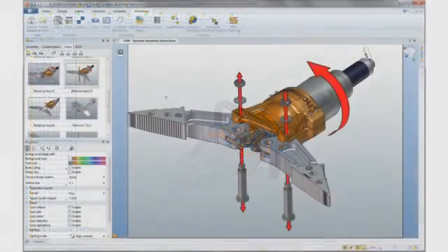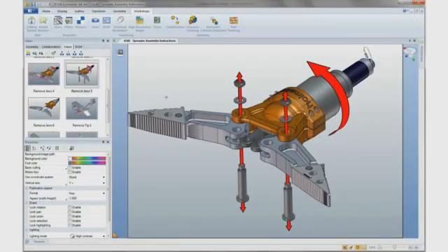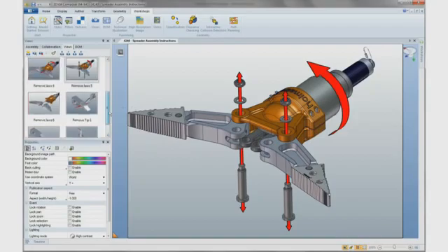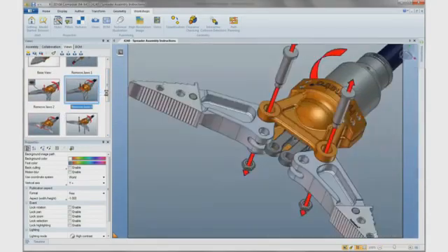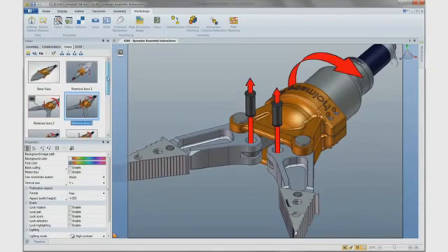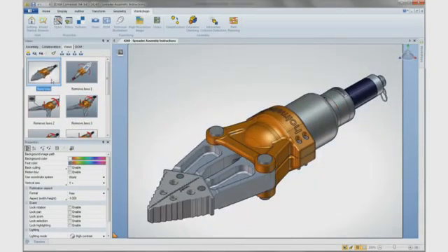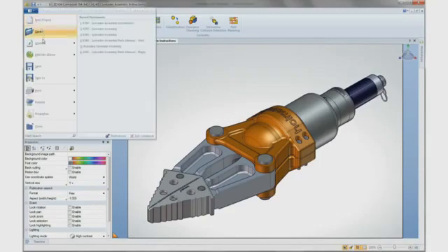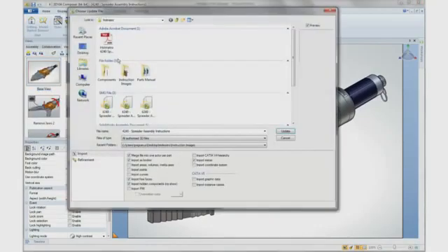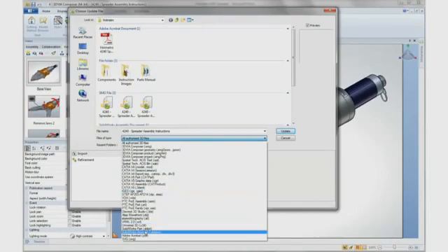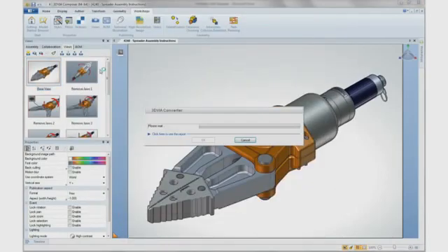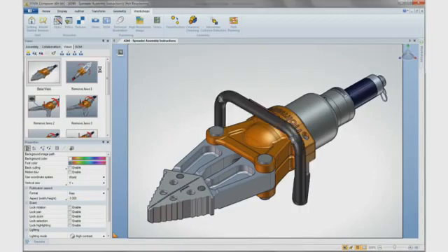The creation of this manual was well underway before the design had been finished. We can see that none of the views contains the handle assembly that was recently added as a design change. Thanks to SolidWorks Composer's associativity, we can see how a change within the engineering software will affect the work in progress. As the design change is made, the documentation can be made current with a simple update command.